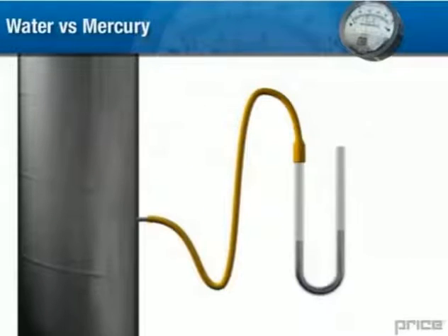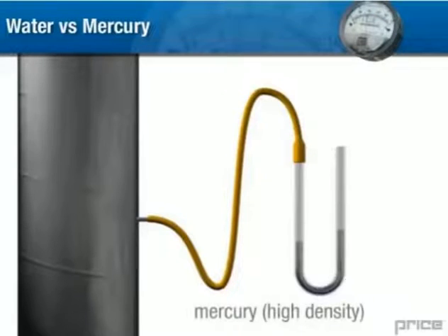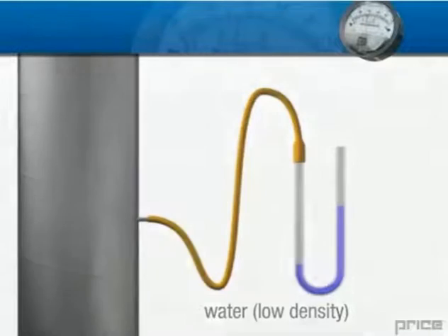When measuring pressure, we must use different liquids for high and low pressures. Liquids with higher densities will displace less for a given pressure. Therefore, a liquid such as mercury is better for measuring high pressures, and we would express these measurements in inches of mercury. For better precision at lower pressures, we would fill the manometer with water and express our measurements in inches of water. For the purposes of measuring the relatively low pressures in ductwork, water is more suitable.